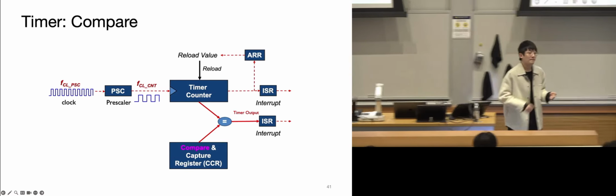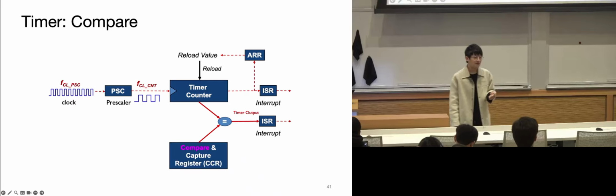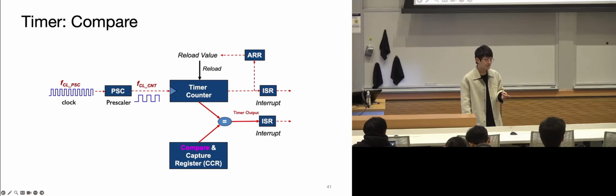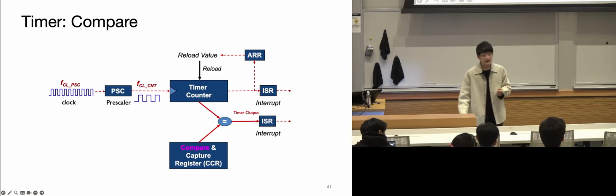Yeah, so in that case, that's right. They could use the interrupt to set the OCREF. So then, imagining an upcounting thing, the act of reloading would also need to generate an interrupt so that it cleans the OCREF, right? Because when it reaches the top, yes. Okay, so it would also have its own.